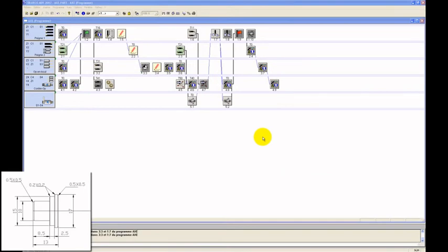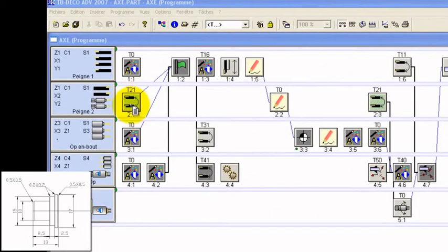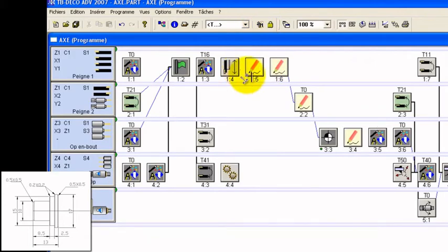So we're going to position our icons in our operations lines here. In COM2, we have in 2.1 an indexing of our roughing tool. In COM1, we are going to add the indexing of our finishing tool in 1.6. We are going to position our bar at 2.2 millimeters so that we can engage in 2.2 our roughing tool.